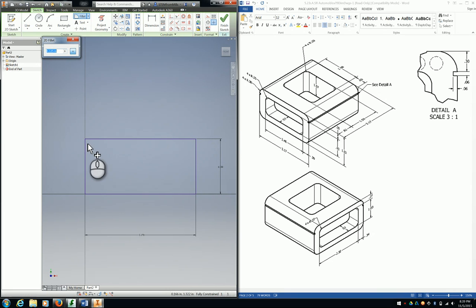What a fillet does is basically curve the edges with a given radius. It's as if we put a circle up here and just round off with that circle. So circles have radiuses, and if I look here, this outside curve has a radius of 0.3. The 4 times on that means that there's 4 sides. All 4 corners have the same fillet radius. Well, I should not have pressed enter. So there we go. We got a radius tool.